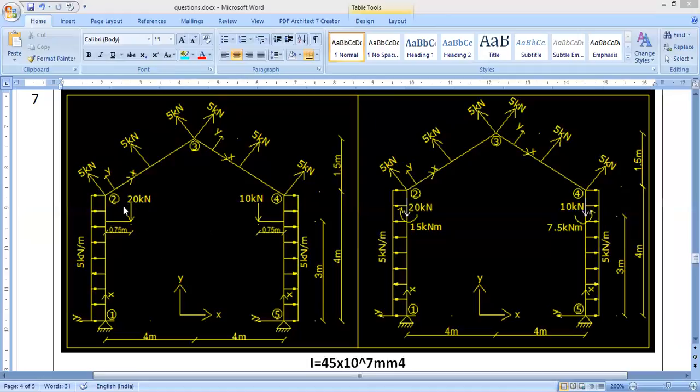For that, what we do instead is convert this load into an axial load and a moment. See this, if you add equal and opposite loading here of 20 kilonewtons, one downward and one upward, then this load and the upward load, separated by a certain distance, will form a couple.